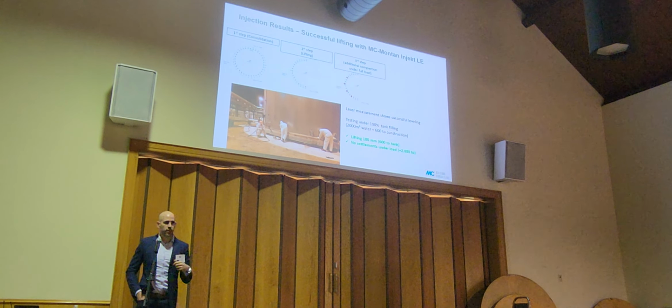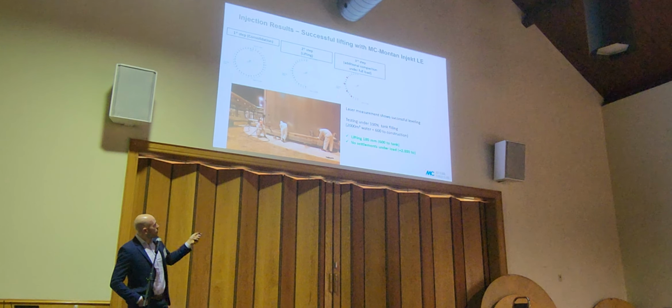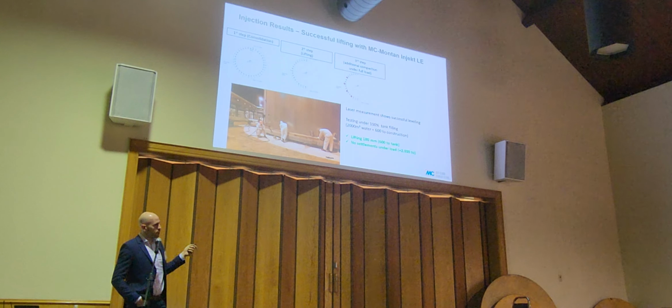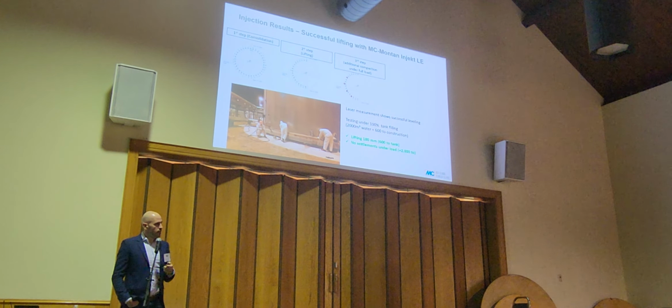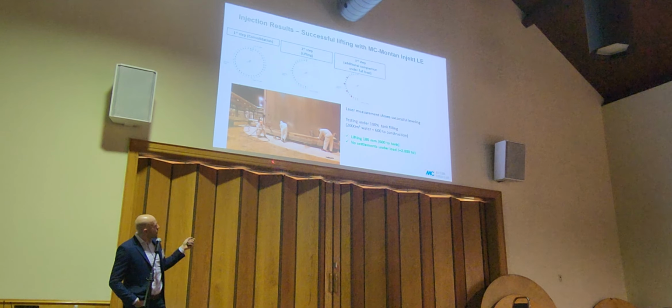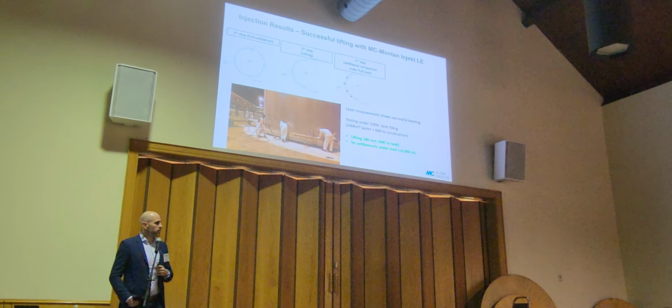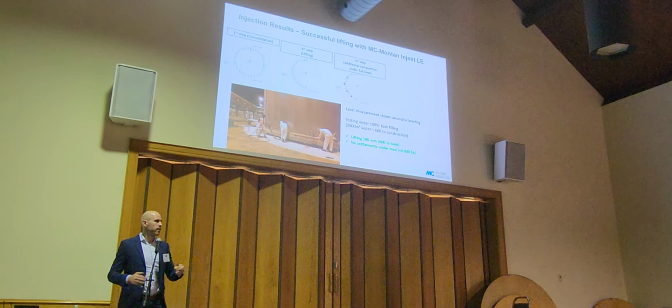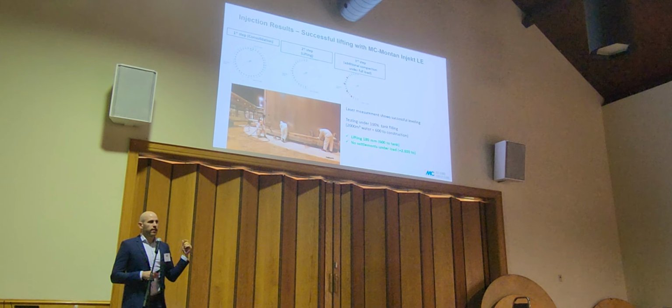So we did it in a lot of points to prove it, and then in addition, he filled the tank to the maximum. So we had 600 tons of construction plus 2,000 cubic meters of water, and altogether this could be done without any additional settlement. So it was proof that now the tank is in the right level, and it stays also if it's full. And the important thing is, we are not lifting by pressure of the pump. We are lifting only with the resin performance. That is very, very important at that point.